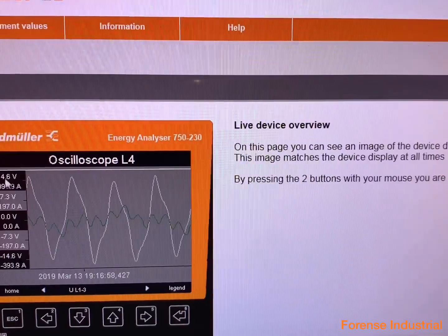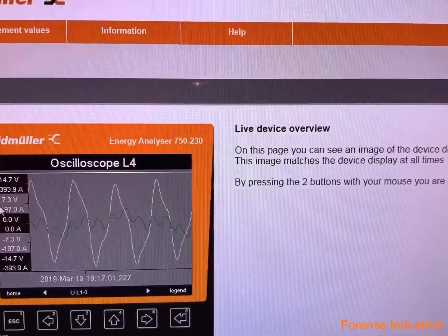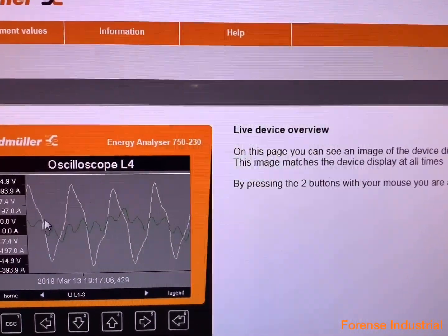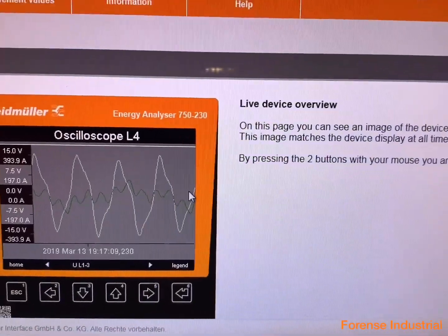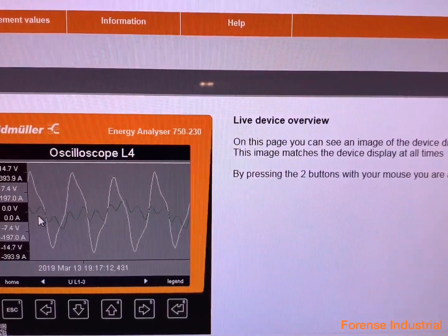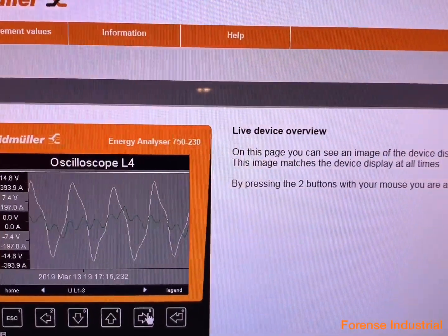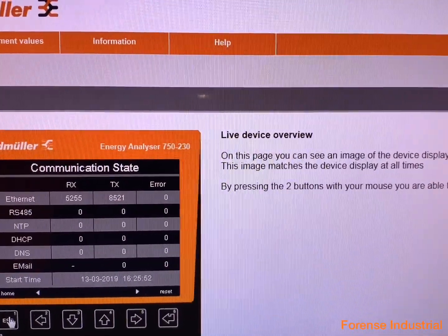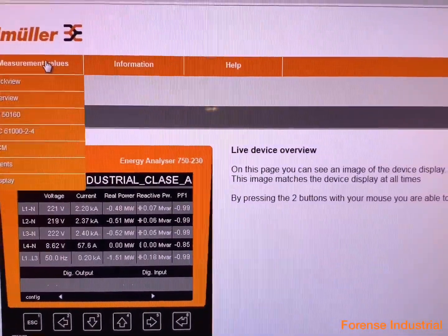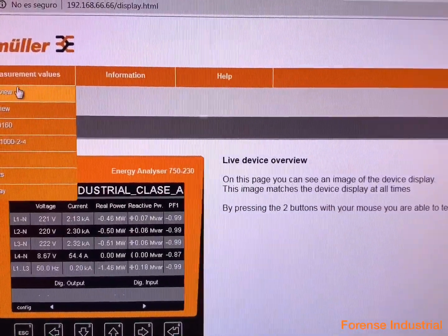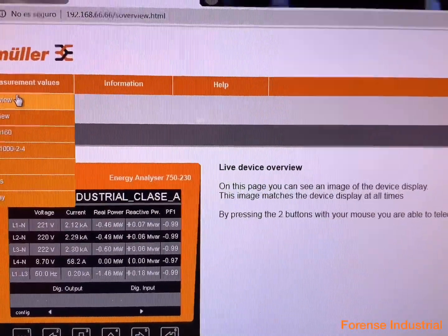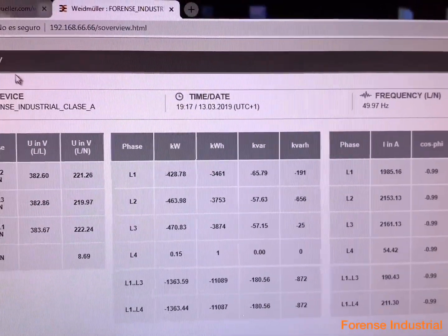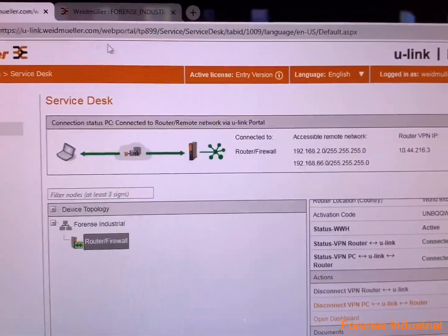We have voltage, it's not good. See here, voltage is not good. And then the current has this form. Maybe it's a triplen with 150 Hz. It's very useful to do that. And okay, that's all at the moment. We have the connection that worked well, and it's possible to have all reports in remote mode. It's very easy if we use the U-Link solution.